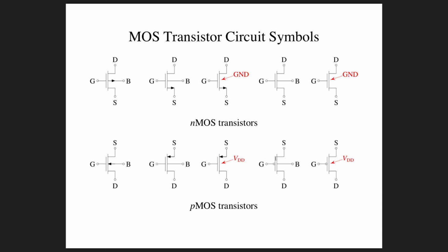For the PMOS transistor, we have to make the gate go low to turn the device on. Whereas in the NMOS transistor, there is no bubble, and we have to make the gate go up to turn on the device. And so people do use these symbols very commonly for digital VLSI circuit design in CMOS. And they also actually do use these symbols in analog circuit design.